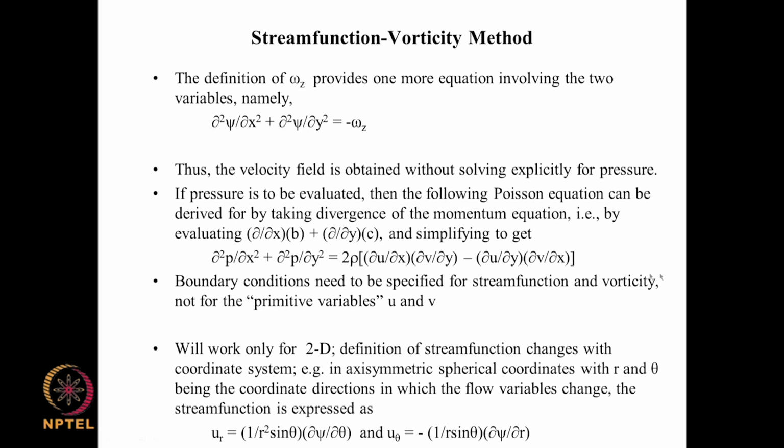And what is good about this equation is that it is like a Poisson equation, and by the time you have come to a solution for p, you already know u and v. So you can evaluate these things. You can evaluate the right hand side, and then you use finite difference approximations for this and this, and you can get a pentadiagonal matrix for p, and then you can solve it to get pressure.